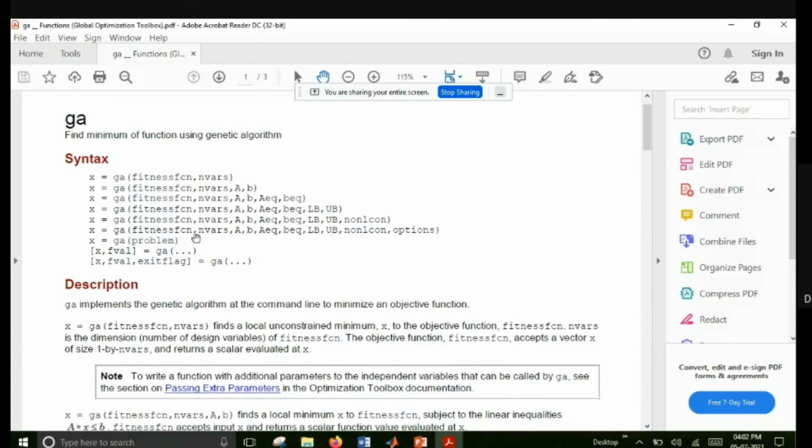GA file. So here also the same solver is GA. The only thing is we have to provide the input arguments in the right manner. In output arguments, generally we desire x values and the objective function value, x and f value. The exit flag and that other information are redundant, right? But we have to provide all input arguments in a particular sequence only.